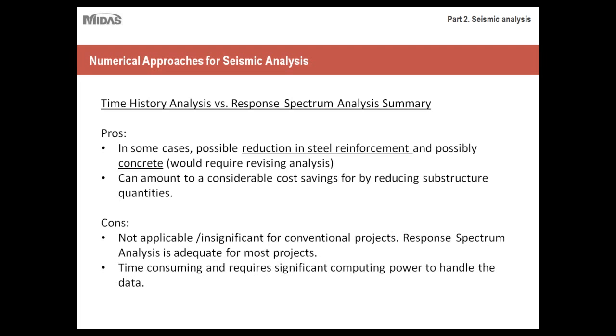And then it's time consuming and requires a significant amount of computing power to handle all of the data. So that's where numerical modeling programs come into account. Even though you can save a lot of time with numerical modeling programs, time history analysis in and of itself is still a very lengthy process. So if you decide to go with a time history analysis, just make sure first and foremost, one, that it's worth the investment, and two, that you're properly equipped to handle it.